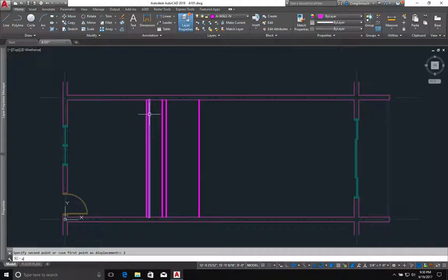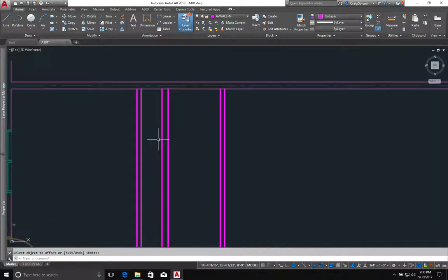Okay, so there's that. Offset, no, not 5 feet, offset 5 inches. And what I'm doing, this seems a little weird because you're saying, well, if this whole thing is the bedroom and that whole thing is the closet and that whole thing there is the bathroom. It's like, no, but I'm using my lines just to sketch things out. I don't want to get exact, perfect total sizes just yet. That's going to come in a little later.